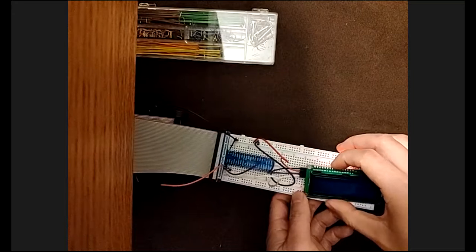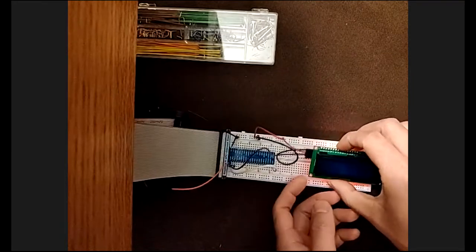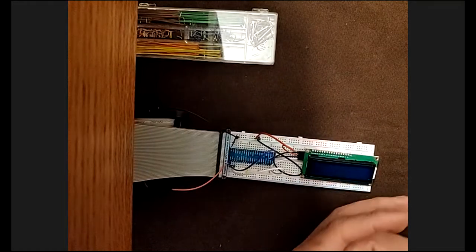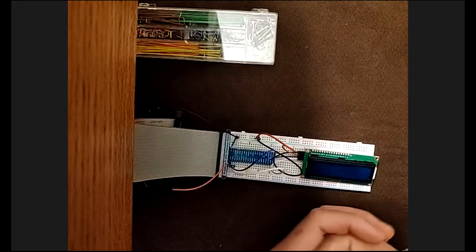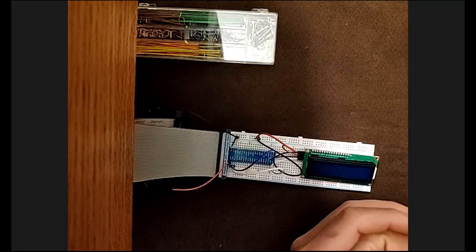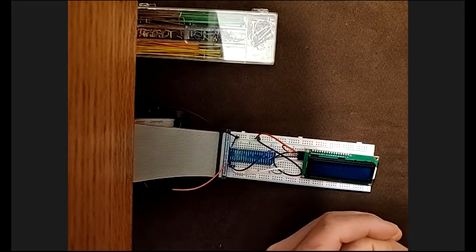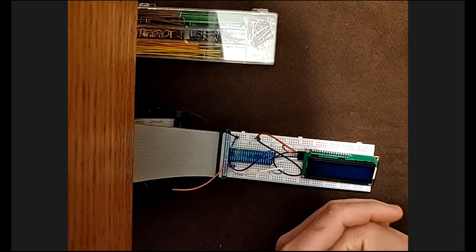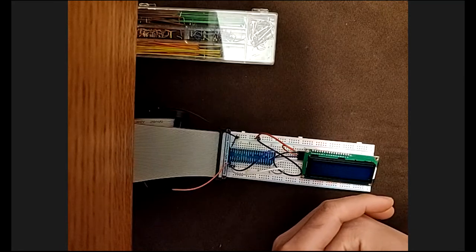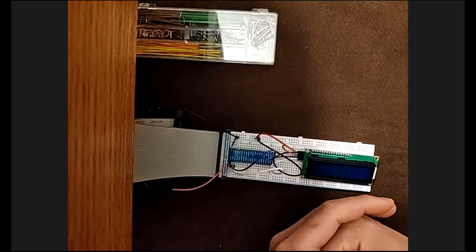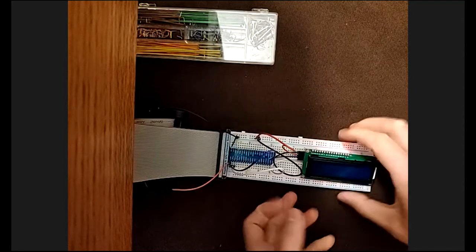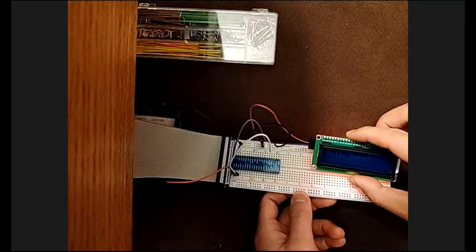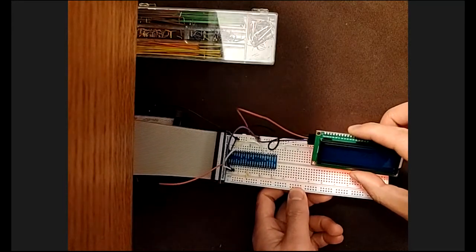And typically, whenever you connect the devices, be very careful not to connect 5 volts. You may potentially damage your Pi and your device as well. So only when you're certain you know what you're doing, then you connect the 5 volts. A lot of times, in order to connect to 5 volts, you have to put some other components in between to protect the devices. In this case, with the LCD, it turns out that it is good enough on its own. Okay.